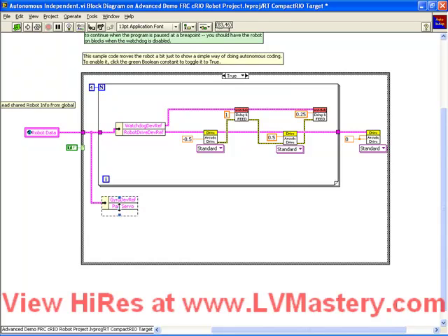The only other comment I'm going to make is related to data such as the switch off time. Just because the data type has been added to our typedef, that doesn't necessarily mean that the data values that we had in the teleop mode will be available in the autonomous mode. If we were to run this right now and make our necessary modifications, I won't right now because I don't want this video to go on too long, and you can make the same modifications you saw in the previous blog entry where we did it to the basic framework. But if you were to make some modifications using the gyro and the pan servo, you'll find that the references are there, but any other data you added is not available. Let's take a look at the reason why.